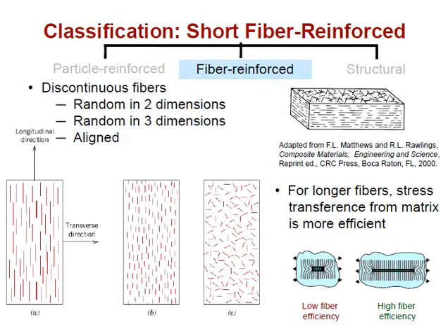Okay, fiber reinforcement kind of comes in 2 flavors, continuous and discontinuous. So this slide addresses discontinuous fibers. You'll hear this going under the term chopped fiber quite often. You can have that discontinuous or chopped fiber randomly oriented and end up with a composite that is more or less isotropic in nature, or you can align those fibers and have something that's going to have more anisotropic properties, more akin to what a continuous fiber composite would have.